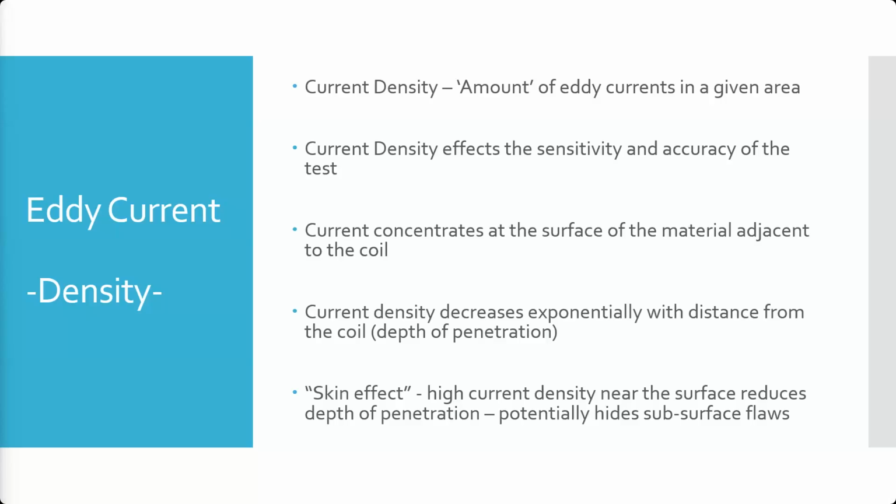So, what I'll get here on this thin flange is going to be different than what I'll get on the thicker part. And what I'll get on the very edge of the flange is going to be different than what I'll get near the side, because this vertical section chunk of metal is going to affect my probe.